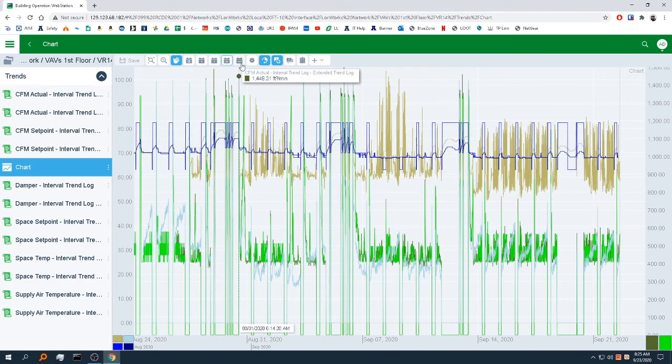The month perspective of these gets a little bit clouded, but still you can see the pattern of it shutting down each night and on the weekends. Just as a good indicator, if those lines were just solid across here with no dips, you would know that that unit is running 24/7, and so something needs to be addressed.